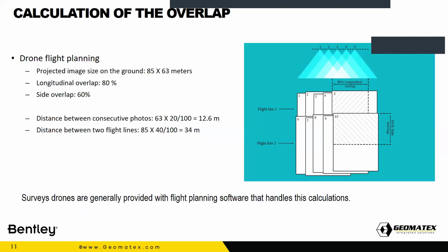So we are here speaking about overlap between 60 and 80%. And this overlap should not only be a forward lap, it also should be a side lap, because you don't want to see your model from a side perspective. You need to see it in 3D mode. So all the four faces of any cube should be very similar in accuracy. In this case, you should keep a consistent overlap and side lap from 60 to 80%.